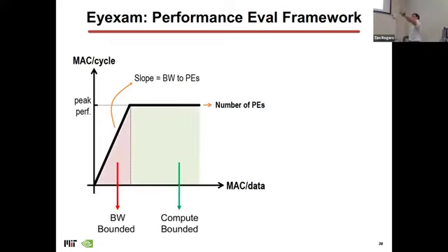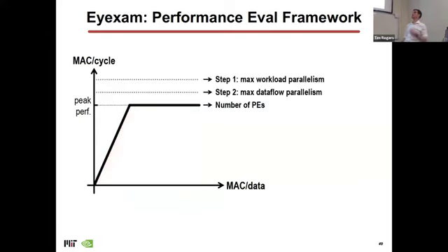So you're essentially bandwidth bound if you're in this region, because your workload doesn't have enough work per compute to saturate the compute units. Once you cross the boundary, you're now compute bound because you're using the PEs and your workload has enough compute in it. Now, there are theoretical lines above what you actually built, right? And this is how they do their performance estimate.